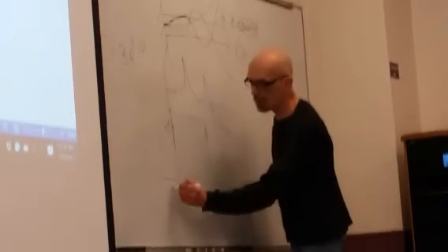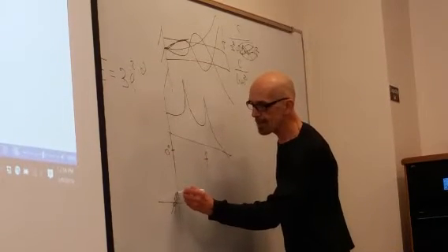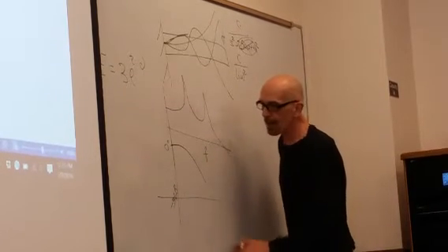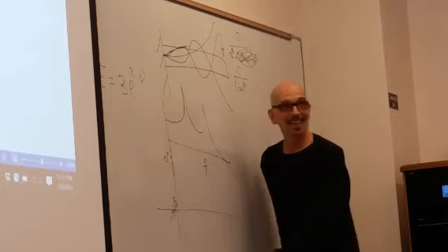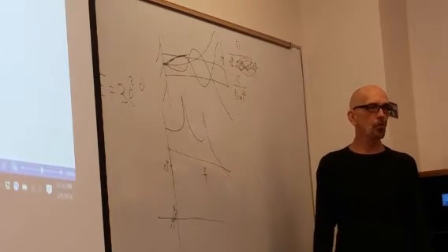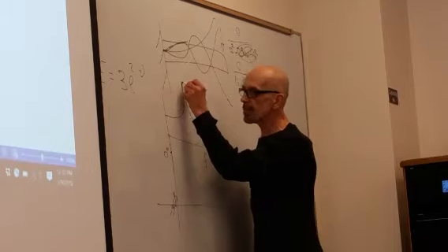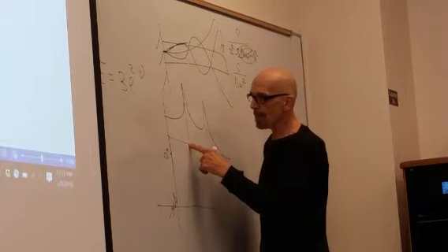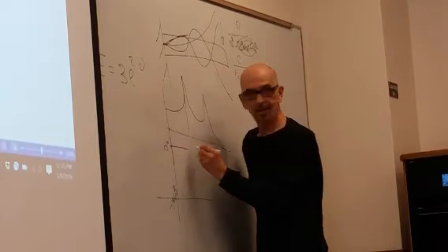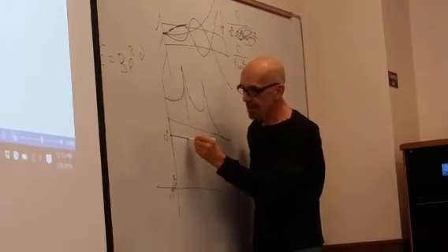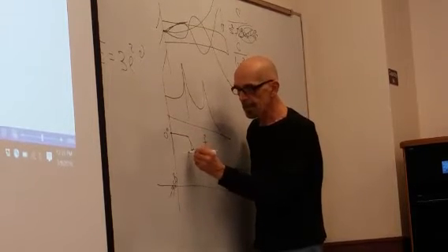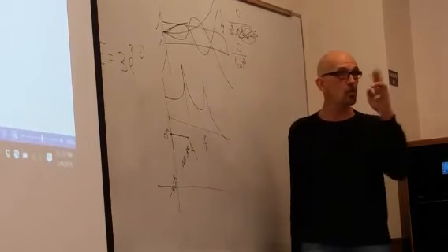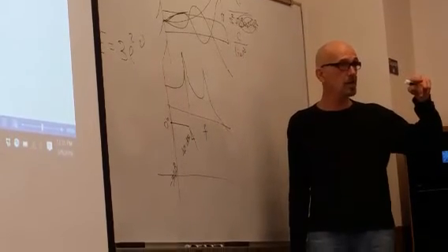So this starts at 0, goes down to minus 360 in the absence of zeros in the plant transfer function. And, all right, let's do a straight line approximation to this. Real crude straight line. At frequencies much lower than the break frequency, it's constant. Then at this break frequency, it rolls down at 40 dB per decade. That's the slope, because there's two s's, not one. One s would be 20 dB down.